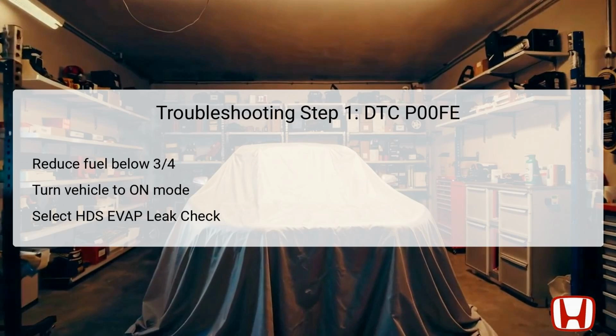Next, turn the vehicle to the on mode, but refrain from starting the engine. At this point, you will need to select the EVAP leak check test using the HDS Honda Diagnostic System tool. This diagnostic function specifically targets the EVAP leak check module and allows the technician to gather essential data on the system's performance, paving the way for further investigation into the source of the error.